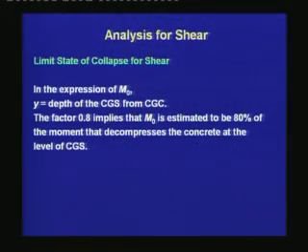Now, corresponding to that moment, if we take 80% of that, that will give me the moment which will decompress the tension face, which is below the level of CGS. In the expression of M0, y is the depth of CGS from CGC.